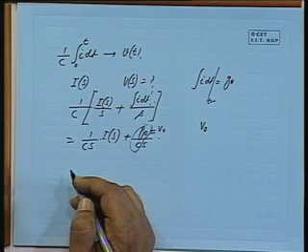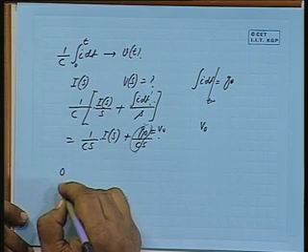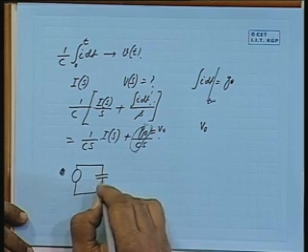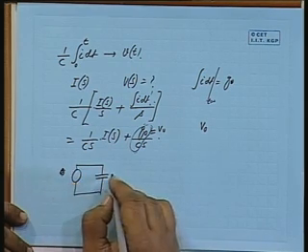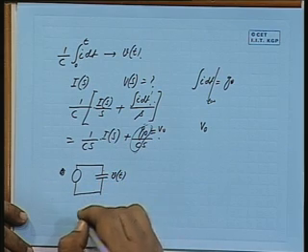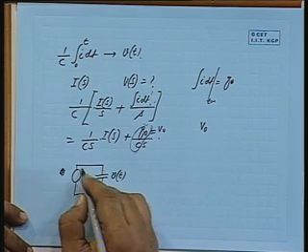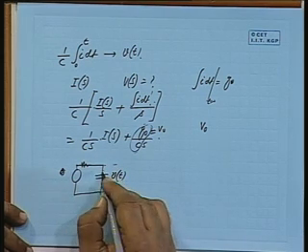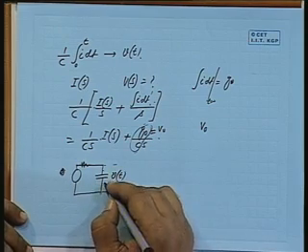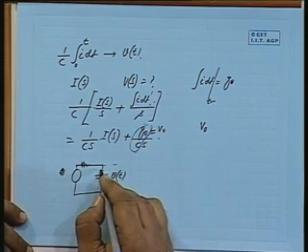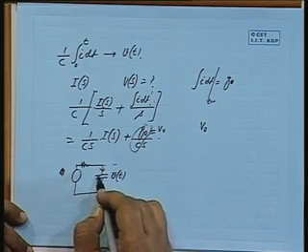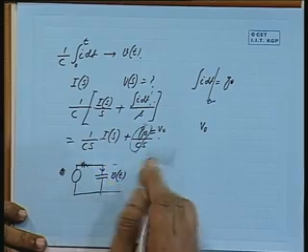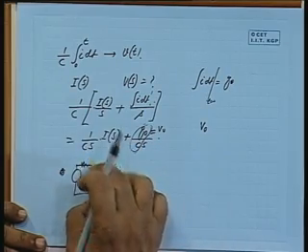So, when we evaluate the voltage across a capacitor, which you are energizing by this, there can be a resistance also, if you want to measure the voltage across this capacitor, then its initial voltage plus, at any instant, if current is i(t), if you want to deal with this problem in the Laplace domain, then I(s) into 1 by Cs, this total sum will be the voltage across the capacitor.